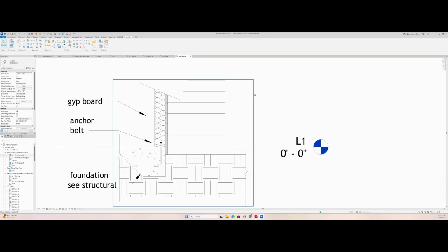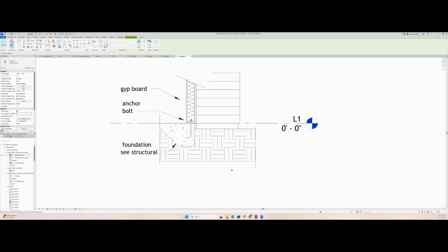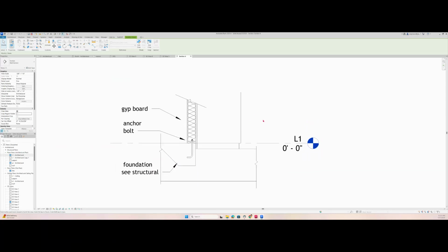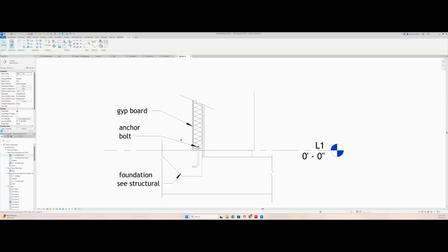Remember, this ugly box here is your viewport. Under extents, you can disable crop region visible, apply it, and then there's no more box around there. There we go. And we can keep going with more leaders, with more annotations. We need to do those things for sure.